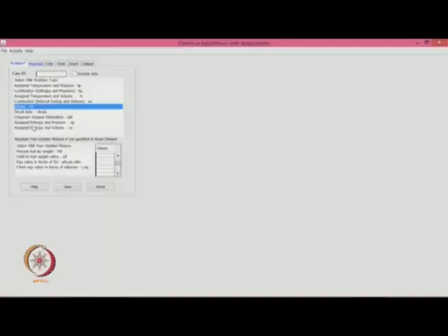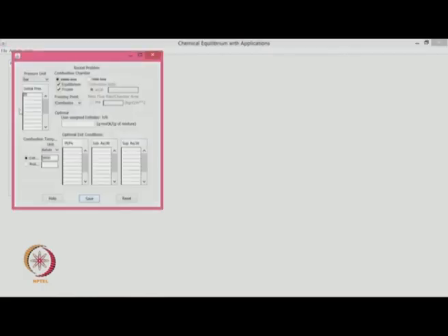Therefore, we do not have anything clicked in this menu here, and if we click at the rocket menu, we have something like 70 atmospheres and 70 pressure ratio. We can also give something like 10 and 15 area ratios. So, we click both equilibrium and frozen flow.